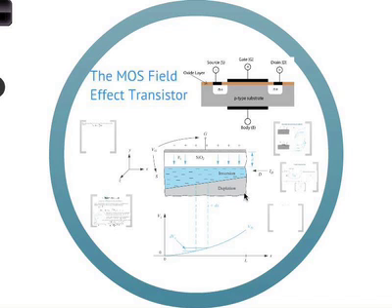The drain to body voltage at some point becomes zero, which means that if they're connected together, this depletion region will basically meet the inversion region, and the inversion disappears essentially. So you have pinch off and you have saturation. Saturation is where you operate the transistor to get amplification. If you just want to use it as a switch, you can operate it in the linear region if needed.